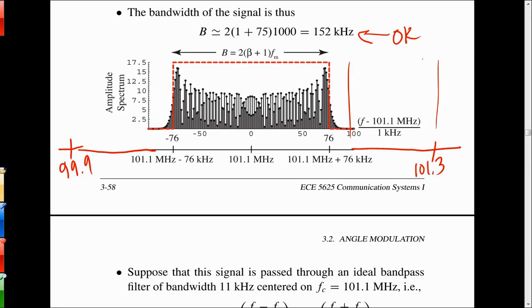It exists, though, because that was an add-on standard that crams another piece of information in the existing allocation digitally to give you higher fidelity, but still not force the reallocation of the frequencies. And AM is the same thing. TV, they just said, clean the slate. We're going to get rid of this old standard and put a new standard in. HD FM said we're going to keep the same standard and try to cram this extra information in there, broadcasting analog and digital together.